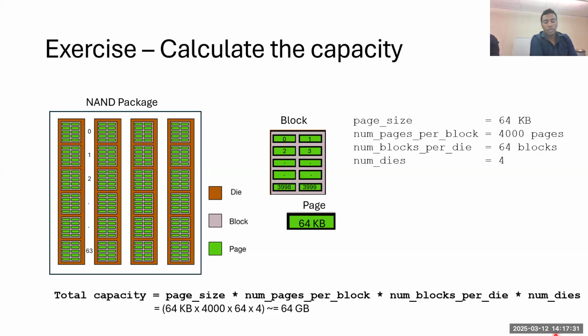yeah, let's say that we are developing the next generation of NAND. So what we will do is, after designing the cells, we will take some empirical data to figure out, like we will stress them with temperature, with writing many times. We will do many kinds of testing. And from that, we will figure out that, okay, this is the optimal window. After this, we start seeing data reliability issues.